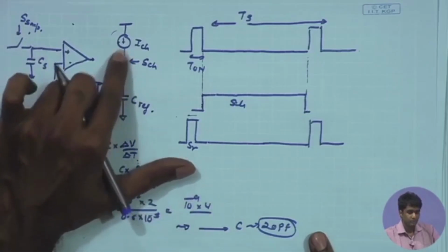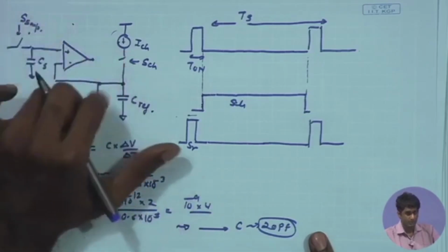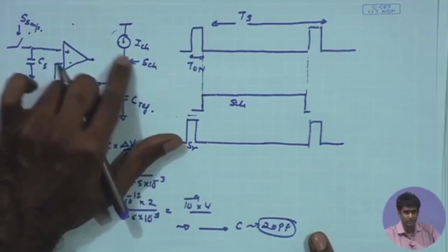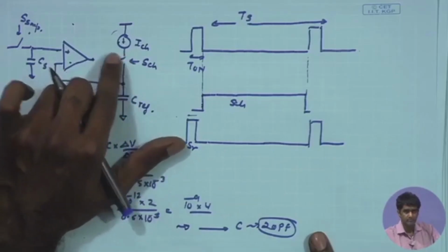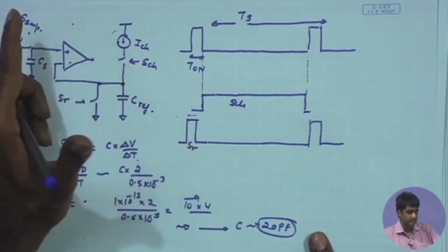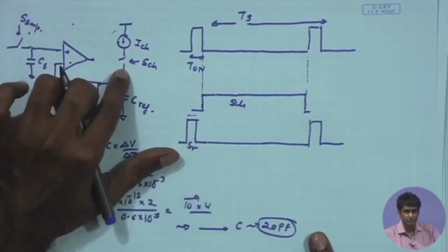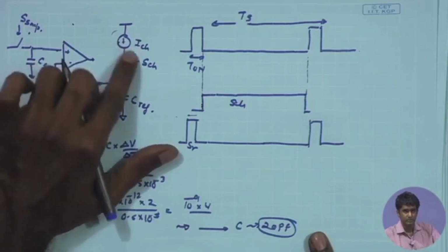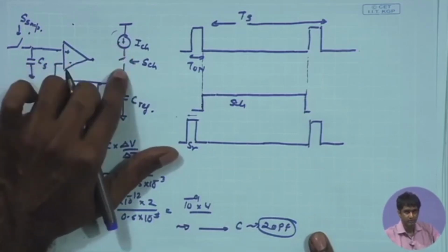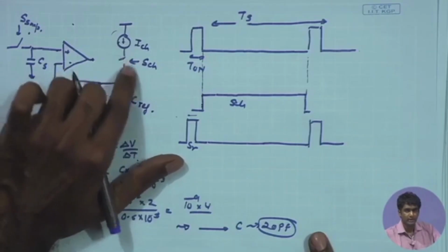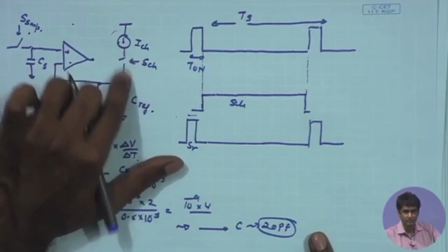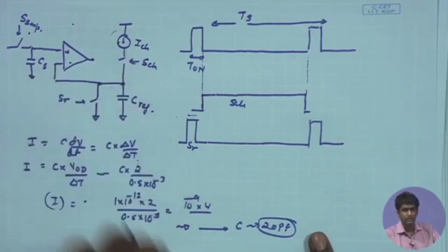As a result, the voltage drop across the switches will be very small, even if they are in triode region and fully on. So we are having 10 to the power of 4 times 10 to the power of minus 7, so less than a millivolt drop across the switches when they are fully on. So we would not expect a significant drop across the switches. As a result, we can use minimum size transistors without worrying about the voltage headroom over here.